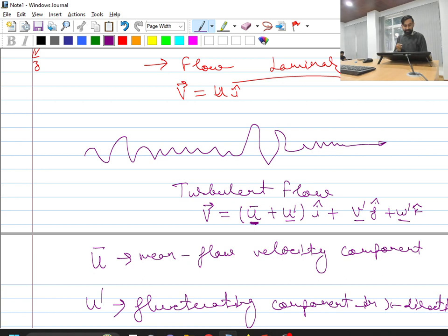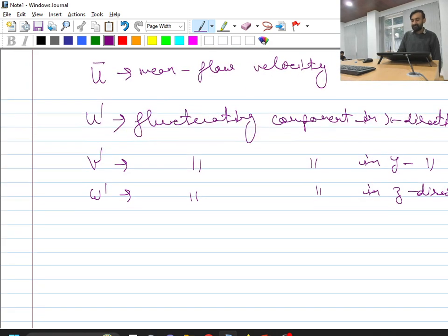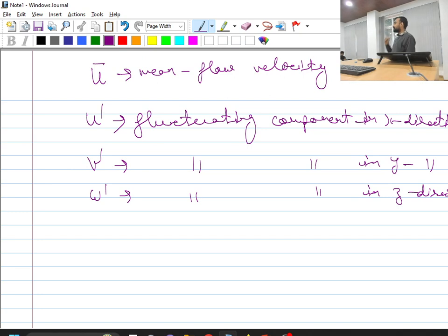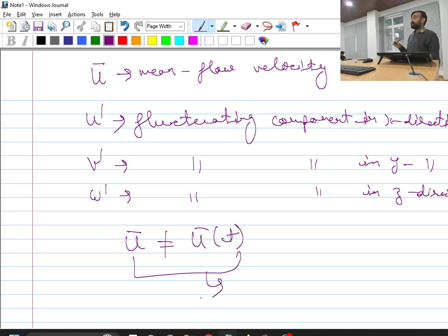On the contrary, you may have some confusion about defining steady versus unsteady flows: I cannot say whether my turbulent flow will be steady or unsteady. This confusion will come to our mind. But one important point we can say here is, if U average is not changing with time, then I can typically say that my turbulent flow is steady for mean velocity.